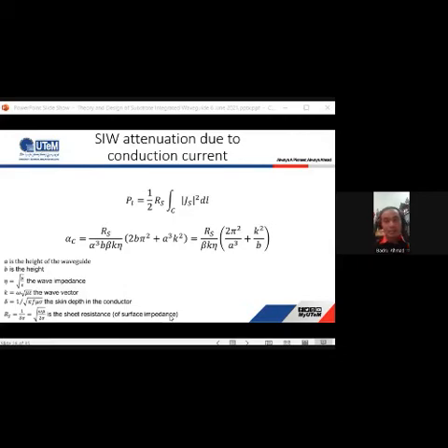As you can see, it is noticeable that lambda c is directly linked to the substrate thickness: the thinner b is than the substrate, the higher the conduction losses. This can be explained by keeping in mind that the ohmic losses are determined by integrating the current density on a path closing the waveguide walls. On the top and bottom horizontal metallic plates, the current is scaled by 1 over b, due to the modification of the field intensity; when b is increased, the field intensity decreases, because it is inversely proportional, as well as the current.